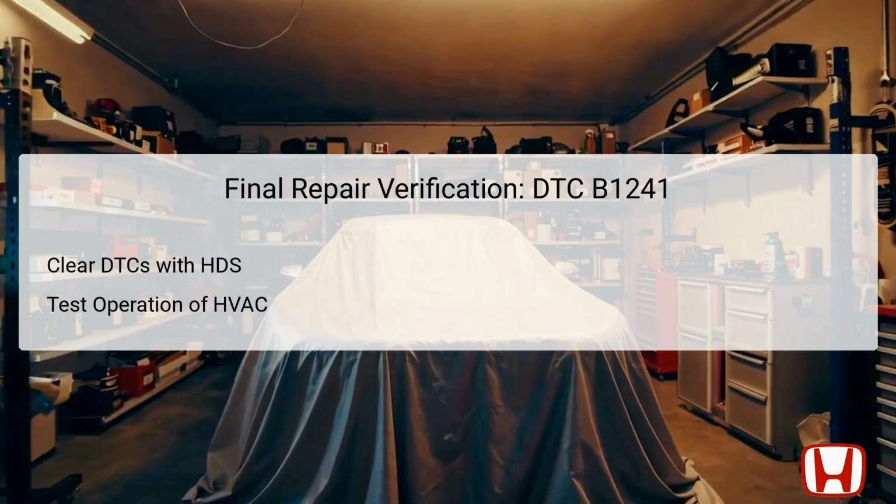Following this, conduct operational tests of the HVAC system to ensure that the blower motor and climate control interfaces are functioning as intended. This step confirms the completeness of the repair work, ensuring the blower motor now runs properly and that airflow is correctly directed as per user settings. This final verification phase is a critical part of the troubleshooting process and is necessary for ensuring trouble-free performance moving forward.